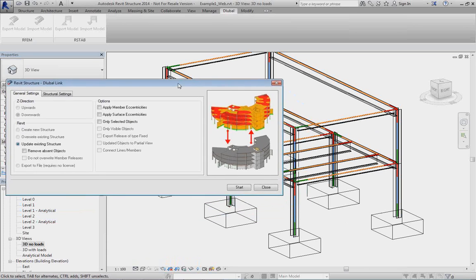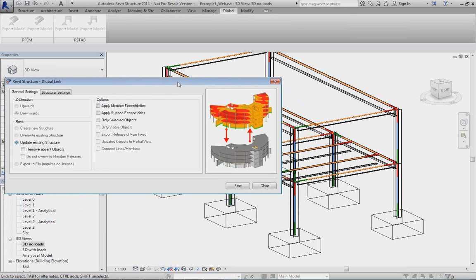So Revit or RFEM compares two models, and we see, okay, there is a cross beam that has the same internal ID and that has a changed cross section, and I take the changed cross section, but I cannot find the column in the RFEM model, but because this check is gone here, I'll leave it there, no matter what is there or not.